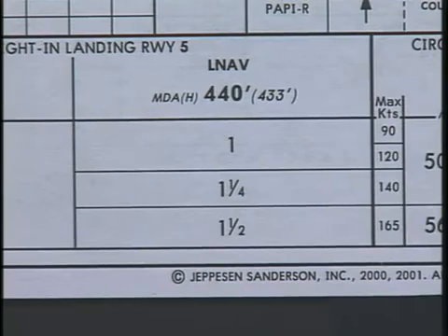LNAV minimums are designed for non-precision approaches that only provide lateral navigation. Because vertical guidance is not provided, the minimums will be published as an MDA.